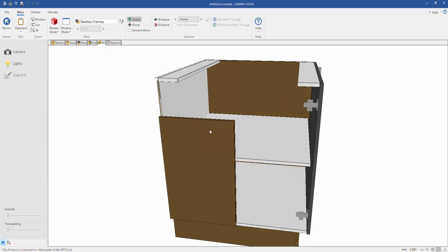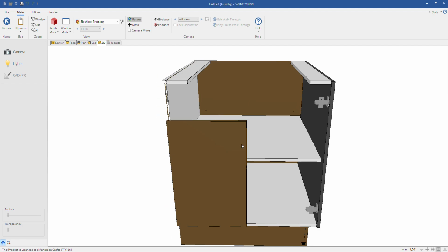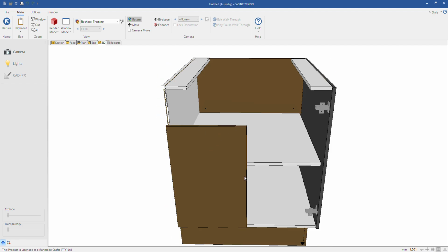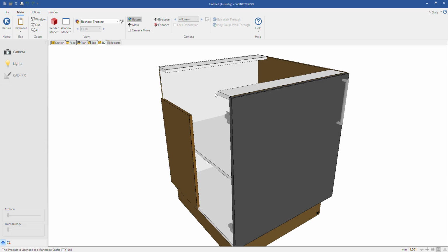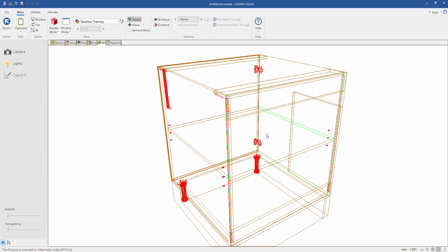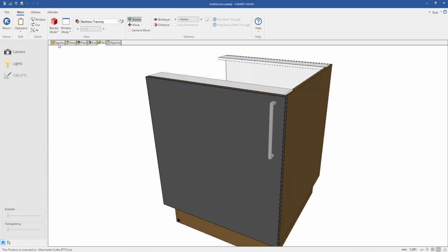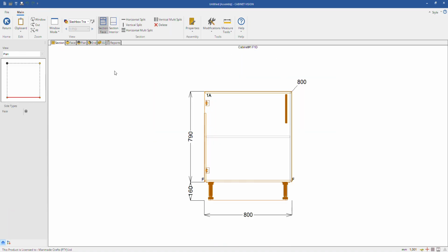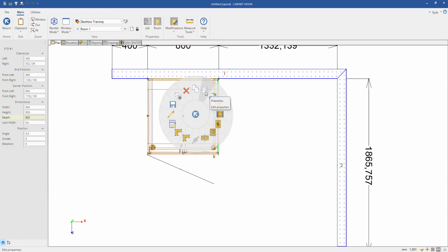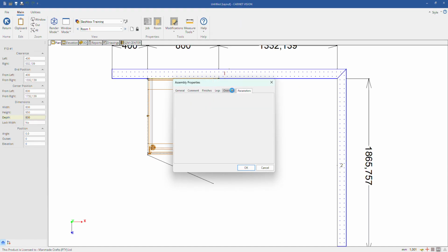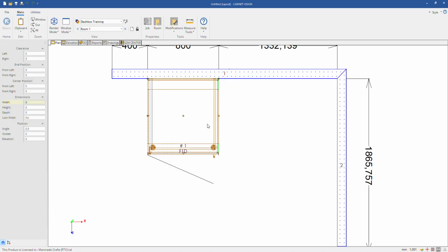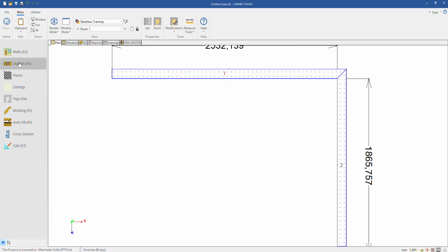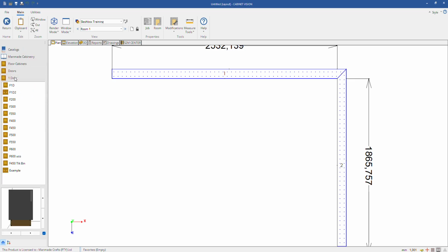As soon as I change the sizes, and we're going to get to it quite a bit later on, but I just want to give you a forewarning. As soon as you change the sizes on this part specifically, it breaks the parent connection that it has with the rest of the case. And it no longer resizes or adjusts with the sizes of the case. So just always be careful of that. But we're going to get into that a little bit later because there are certain things that you can do on the face plan and in view that are very helpful.